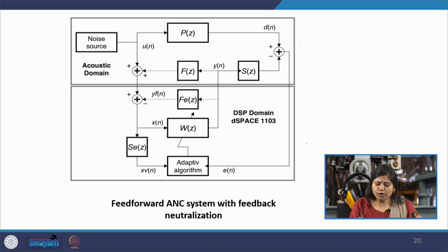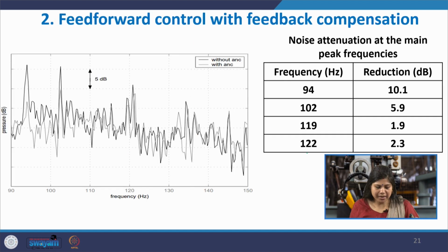And again, I will not go into the details of this method, but rather just focus on what algorithm worked for them. So, what they found was that once they adopted some additional compensation for the acoustic feedback that is being received from the acoustic enclosures in the cabin where the speakers were being played, there was remarkable improvement overall in the reduction.